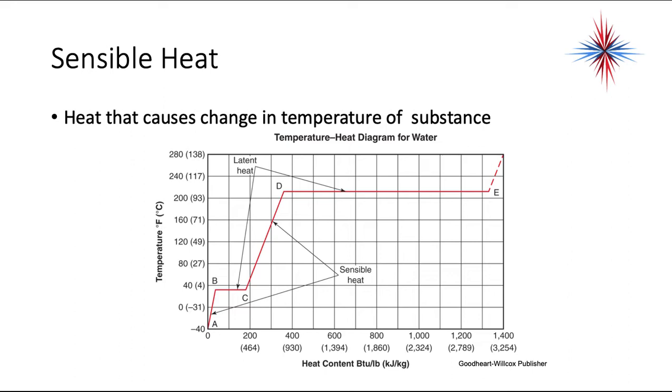We are boiling off refrigerant in the evaporator, and we are condensing refrigerant in the condenser. So in the evaporator, I have my liquid, okay, refrigerant coming in, and then at a certain temperature, I've absorbed all the sensible heat, and now I have to absorb a lot of latent heat, and then it becomes a gas and moves on to my compressor. So all the way through, there are heat content changes going on through the refrigeration cycle, and we'll get more into that.